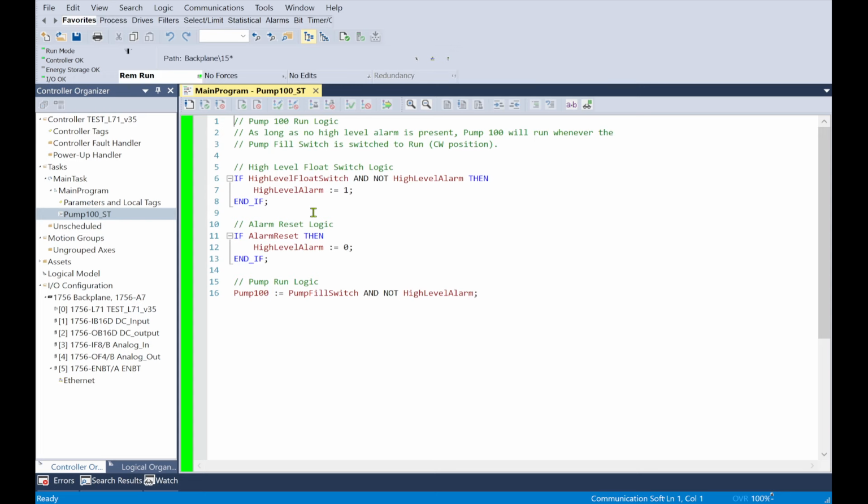But if you're trying to run some fairly complex feed-forward process control with some bias settings and some kind of advanced control strategies, you're going to want to see all those analogs and how they interact on the lines in between those function blocks. Function block is the way to do that. Don't do that in ladder, and definitely don't do that in structured text.